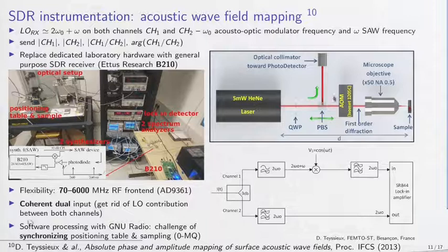Well, we can detect this by analyzing the output of a photodiode directly measured at twice the omega output of the acousto-optic modulator. And if we mix this output with the signal that was used to drive the sample over here, then we will shift 2 times omega 0 plus omega minus omega, the frequency driving the signal, brings us back to 2 times omega 0.